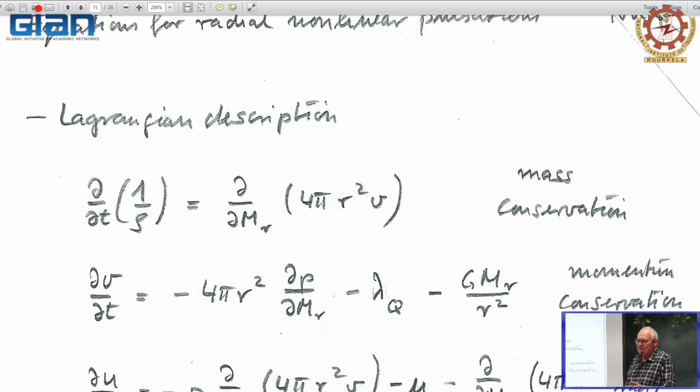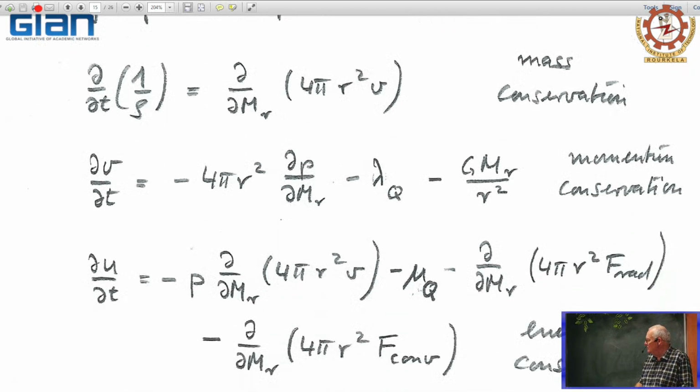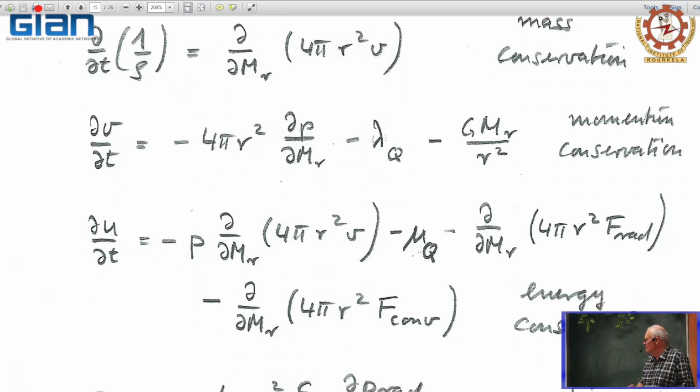It involves discontinuities, and what you have to do is to smear out these discontinuities to represent them numerically. So we have to introduce artificial viscosity, and this term is meant to describe the artificial viscosity needed to resolve discontinuities, in particular shock waves.